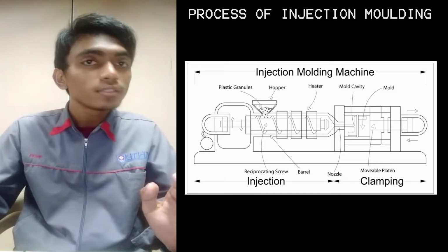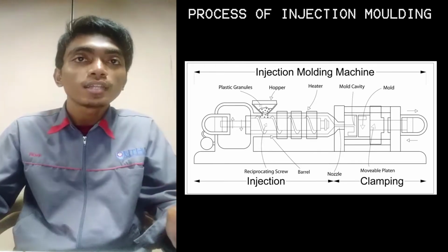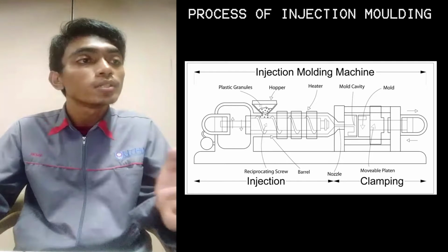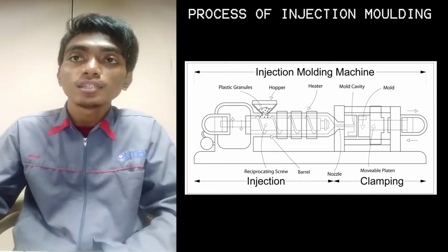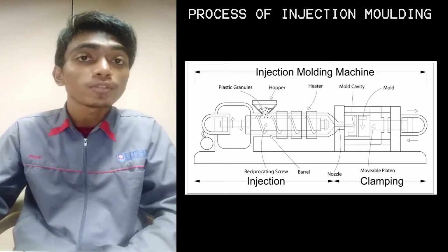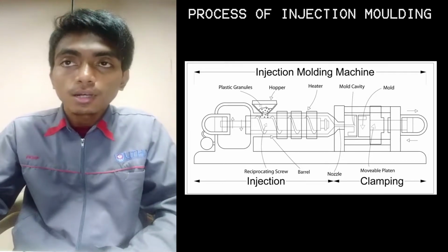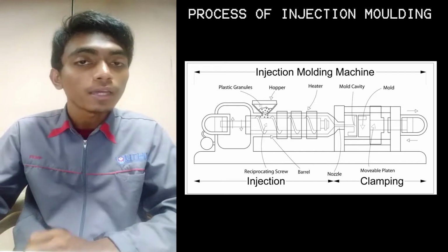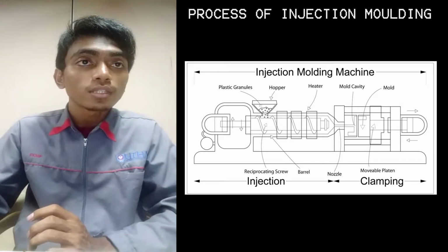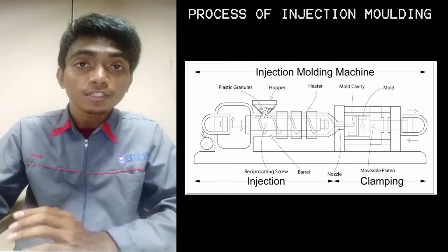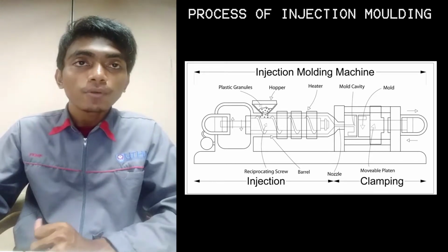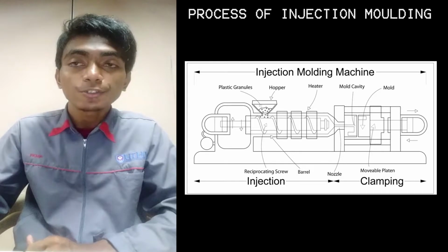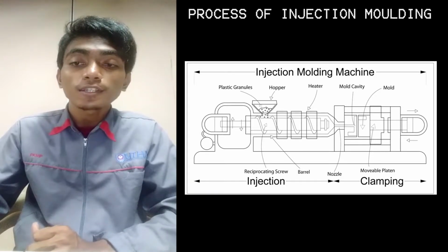or plunger that is usually hydraulic powered. Today, the more common technique is the use of a reciprocating screw. A reciprocating screw moves the material forward by both rotating and sliding axially, being powered by either a hydraulic or electric motor.